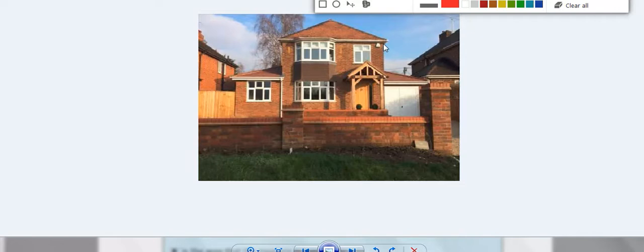So in this scenario, your heat loss walls for this property, this wall here, this wall, but because let's assume that this is a heated extension, your heat loss wall is now extended to the outer skin of this building.